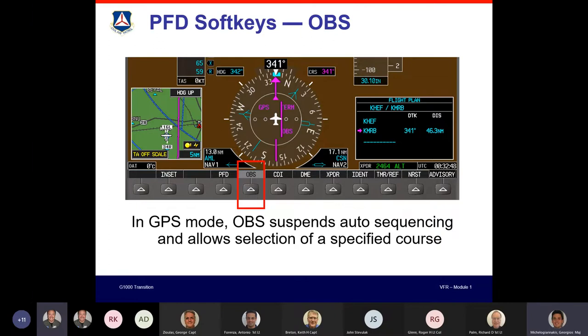It absolutely does have a DME. All right. Unfortunately, they do not. So our planes do not have a VHF DME. They do give you distance information, and they can be entirely equivalent to a DME, but they're GPS derived. They don't have slant range, that's exactly it. But we have GPS derived DME, which according to the AIM is a legal substitute for IFR as well. But we don't have a VHF DME.